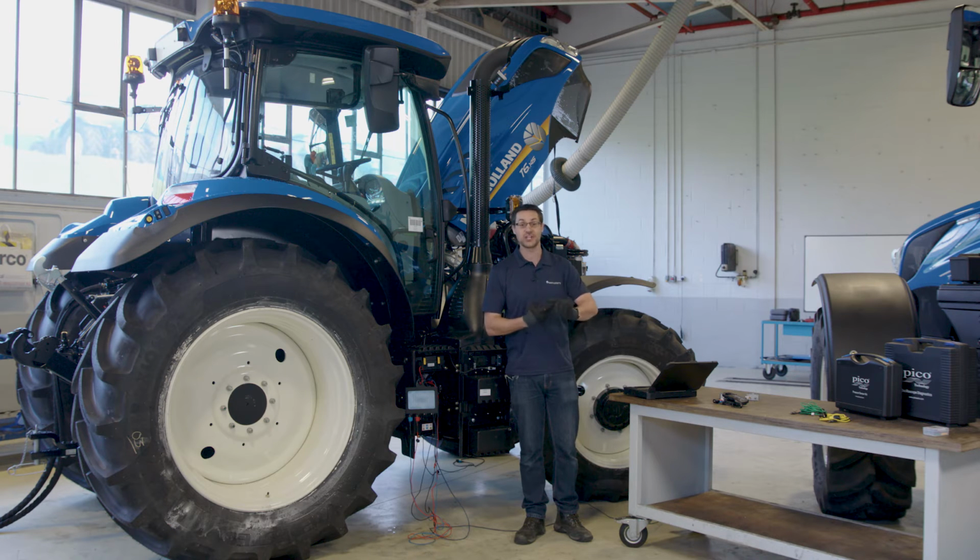It will give us our maths channel, and it will also give us our decoder. Now, most of the time, J1939 sits at 250 kilobaud. It is now moving to 500 kilobaud as well. So it may be that the decoder, which is defaulted in this case, in this guided test, to 250, it may be that if you are getting data that isn't decoding properly, you just need to change your settings to 500 kilobaud. Okay.